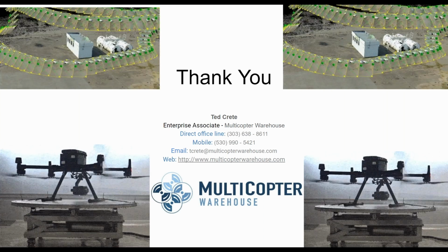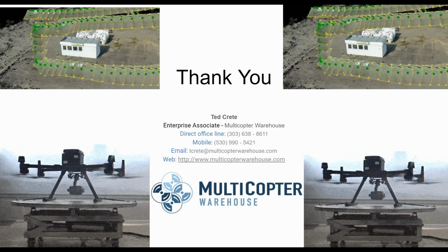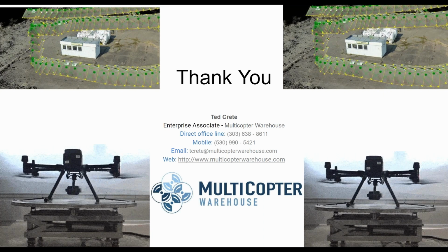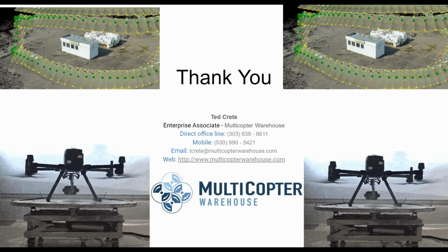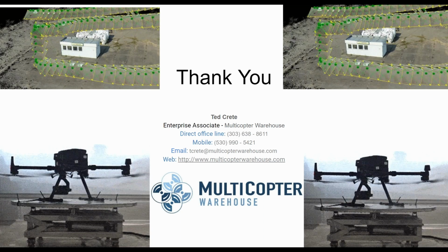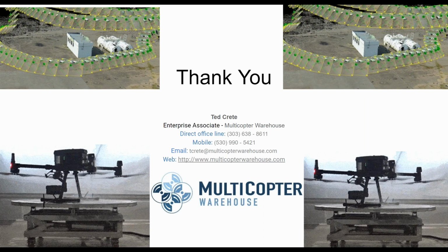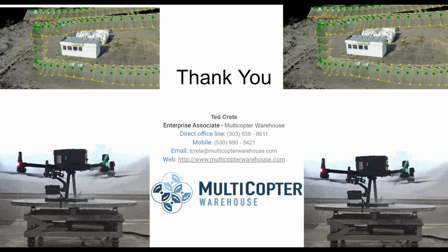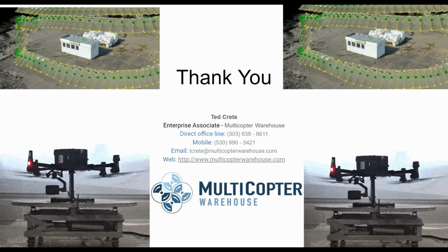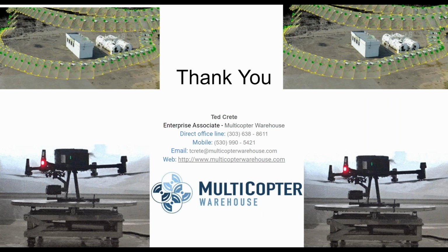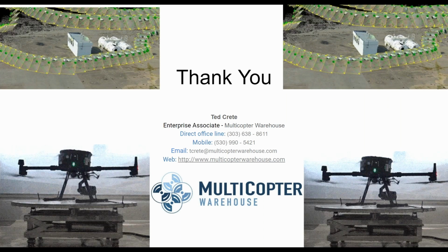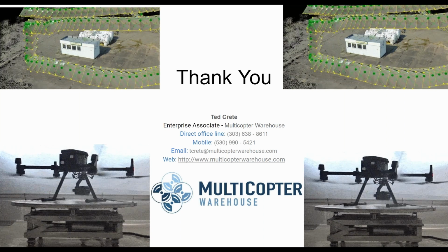So that live RTK data allows you to take accurate data the first time without GCPs. Now, does that mean that you should fly without them? Absolutely not. I highly recommend getting at least 1 or 2 GCPs whenever you use live RTK data as backup and something that you can check your work.